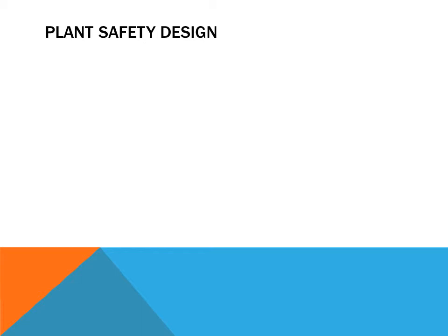Three Mile Island had the design plant safety required to keep the plant from meltdown or catastrophic event. Couple systems: it had the automatic scram feature, which is basically the insertion of all control rods. This allows you to add a lot of negative reactivity all at once, placing the reactor in a shutdown condition. Reactors, though, still will generate decay heat. This decay heat will continue to increase the temperature of water even after the rods go in. So there's a couple water systems that allow you to maintain this cooling of the primary coolant.